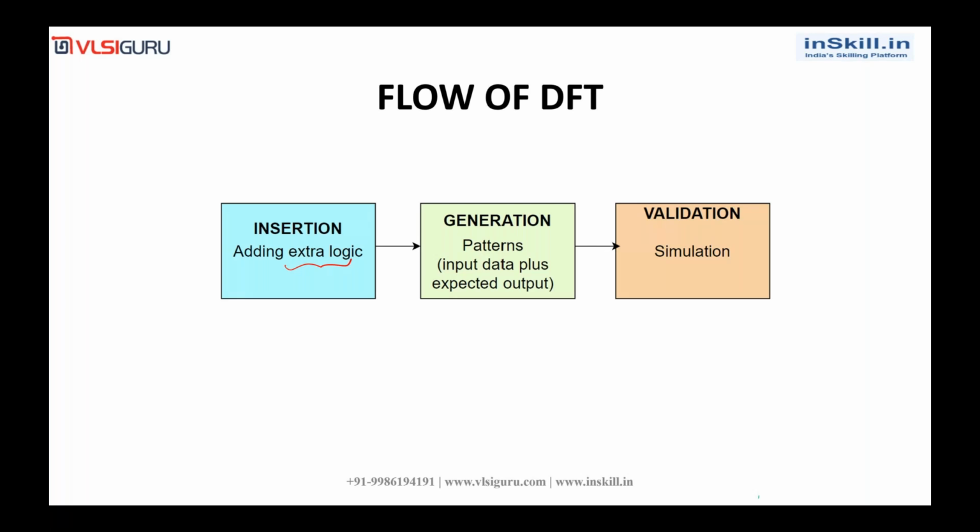Then generation. Generation is nothing but generating the patterns. The patterns will have an input sequence and the expected output. Whatever test patterns we are generating here will be given to test the chip after manufacturing, as we have seen a few slides back.